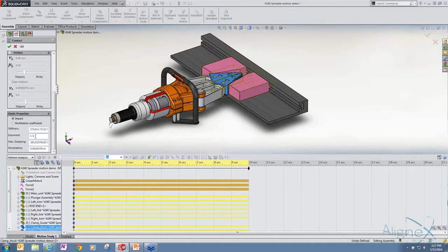They're based on impact calculations and also a restitution coefficient equation as well. So these two equations are actually explained in the help menu, which if I simply push this question mark, it'll bring me right to that page where we can read a little bit more about what's going on. So in this case, I'm actually going to make the stiffness and the damping the same.